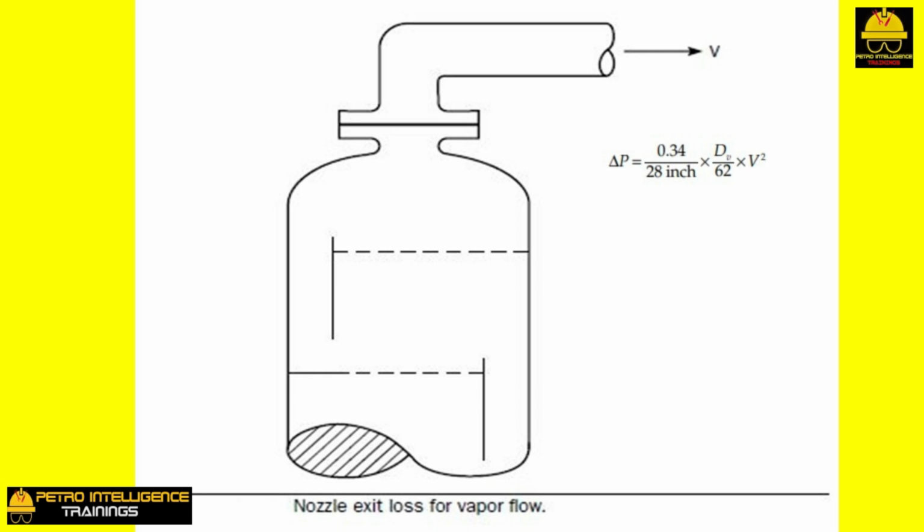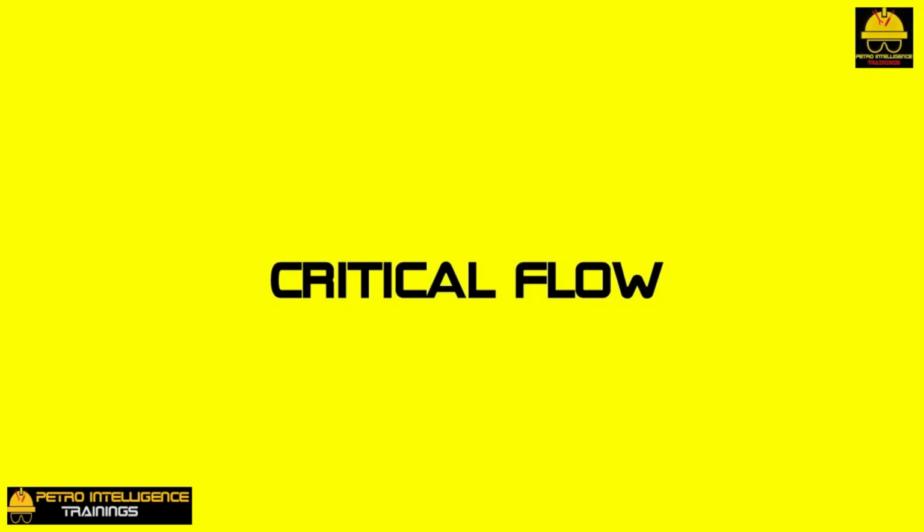This is an important equation to remember. It is the pressure drop through a hole equation. It works for water, steam, air, gasoline, alcohol, and all other fluids, unless viscosity is important. A viscosity of less than 5 or 10 centipoise, cp, or centistokes, cst, such as hot maple syrup, means that viscosity is not important. Critical flow.